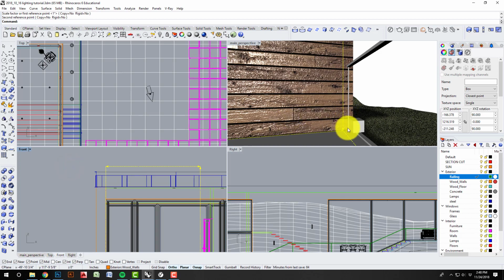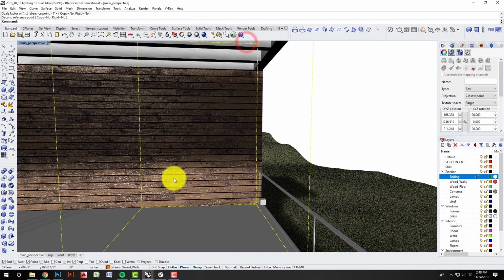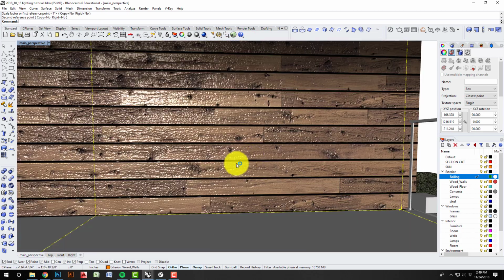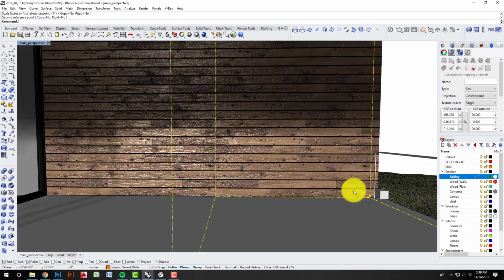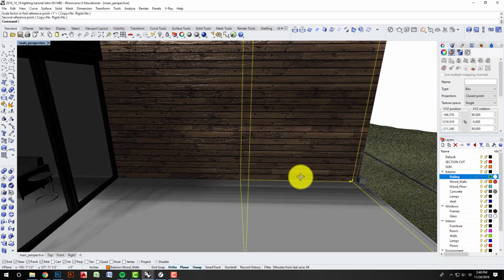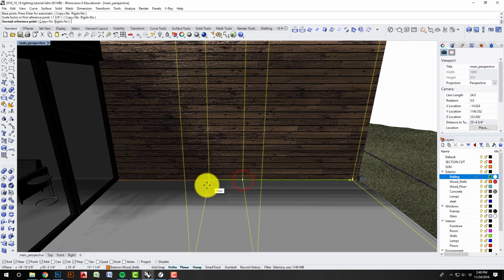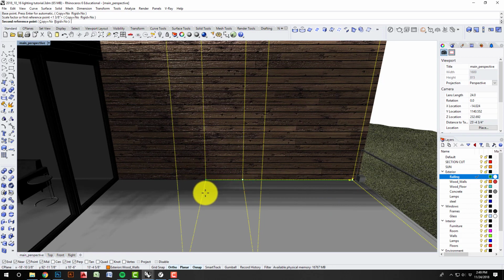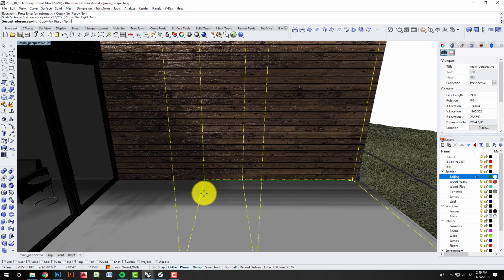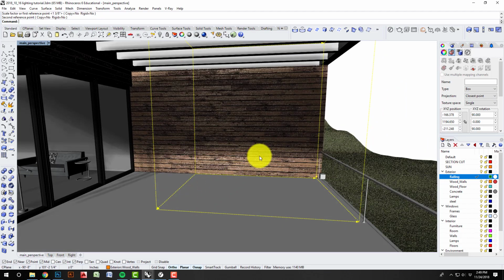Now I know my boards are about 6 inches. And then from there, if I know my board's height, I can just look at the material and start to see if the length is right. And what it looks like is it's a little bit squat. You can see these knots are getting a little bit too small. So I'm just going to, again, eyeball this, scale 1D, and just stretch those out a little bit till they feel like they're in proportion with the height. Because our JPEG we started with was not a perfect square, so it's going to be a little bit wider than it is tall. So we'll go right about there, looks good.